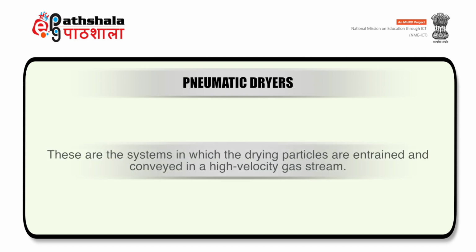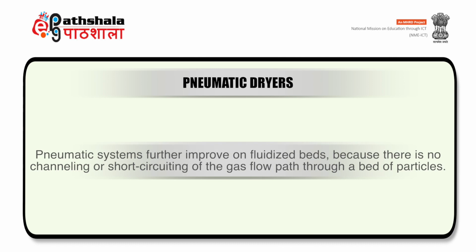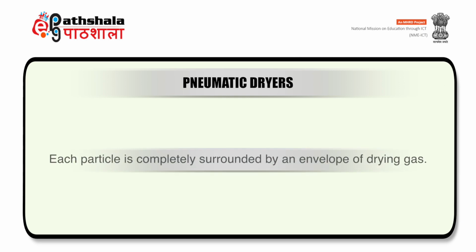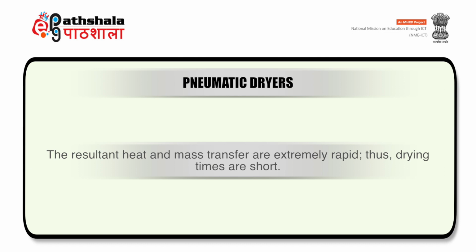These are the systems in which the drying particles are entrained and conveyed in a high velocity gas stream. Pneumatic systems further improve on fluidized beds because there is no channeling or short circuiting of the gas flow path through a bed of particles. Each particle is completely surrounded by an envelope of drying gas. The resultant heat and mass transfer are extremely rapid, thus drying times are short.